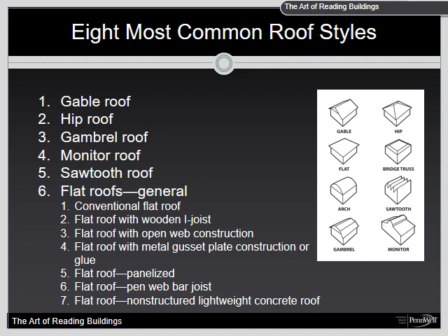Strength. The strength of the wooden roof is in its beams and the purlins in the regions along the building perimeter. The strength of the hybrid roofs is at the girders and the primary steel trusses in the regions along the building's perimeter. Your hazards. Hollow steel pipe of 4-inch diameter can be found supporting the span of wood beams or girders, primarily steel trusses. Expect weakening or collapse of these supports with subsequent failure of large portions of the roof under heavy fire conditions.